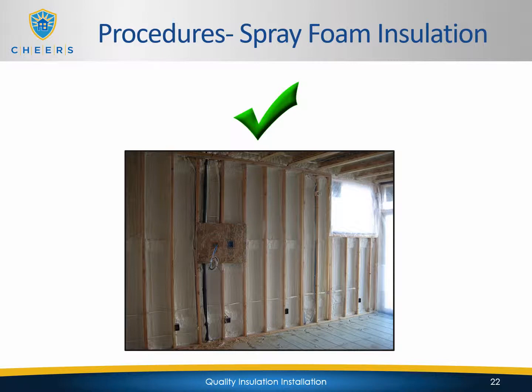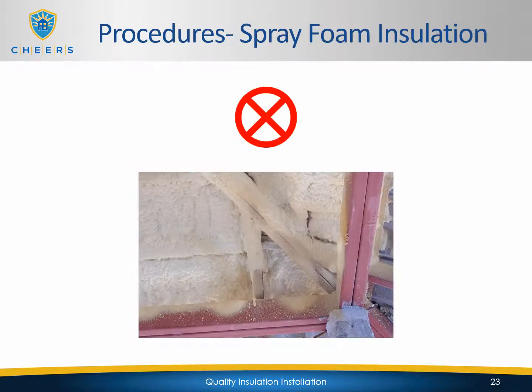This would be an example of good installation. And again, gaps, voids, discoloration, not even all the way around. It doesn't seem like it's filling the whole cavity. It's very uneven. So in this particular scenario, this would be a fail.